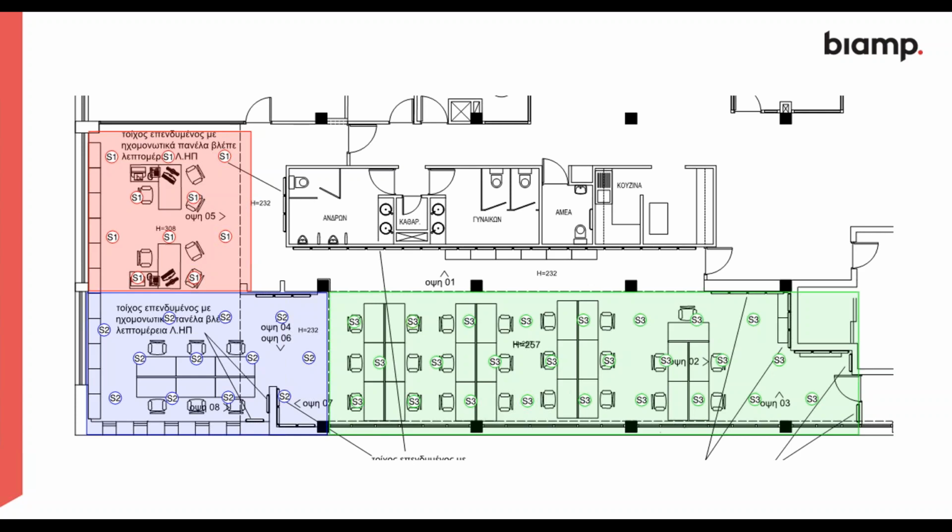Will the emitter output level adjust according to ambient noise in the room? No, we do not adjust the level of sound masking in the space. We tend to have it ideally as a constant level. Sound masking is needed more when it's quiet, not when it's loud. So it's far more effective if you have the masking at a constant level so that it's not noticeable.